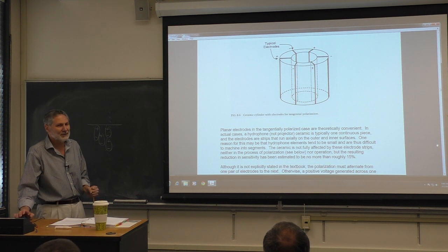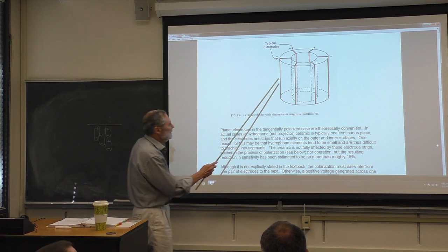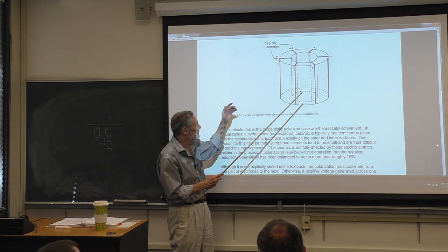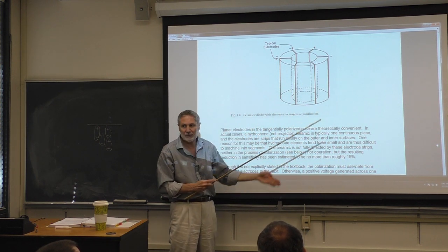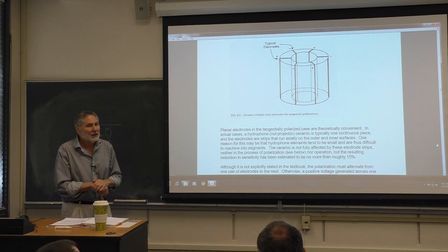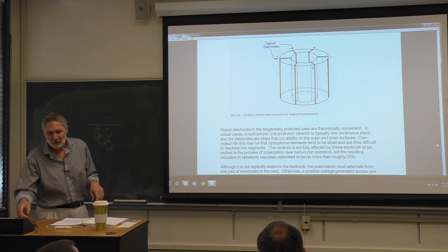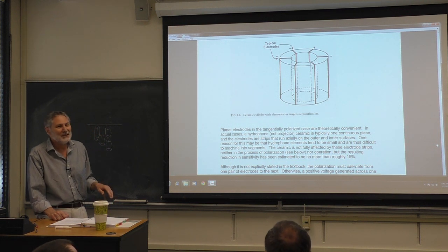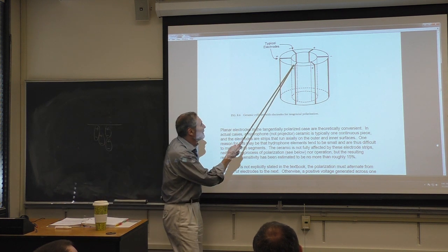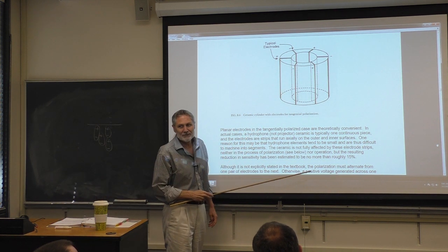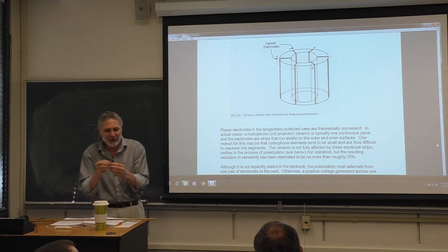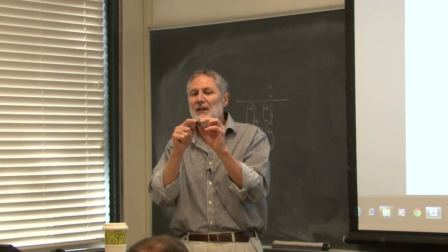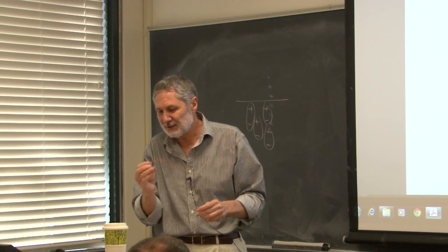Now, there's something else here. So far we've been talking about genuinely segmenting this. This is a different piece than that. There's an electrode in between, okay? That's hard to do for a hydrophone. Hydrophones tend to be small. So somebody realized a trick here. This material is all one piece. And what they do is they put a ribbon, they paint it or attach it somehow, this conducting ribbon on the outside and inside. And I'm going to pass this around, I want you to look at it.